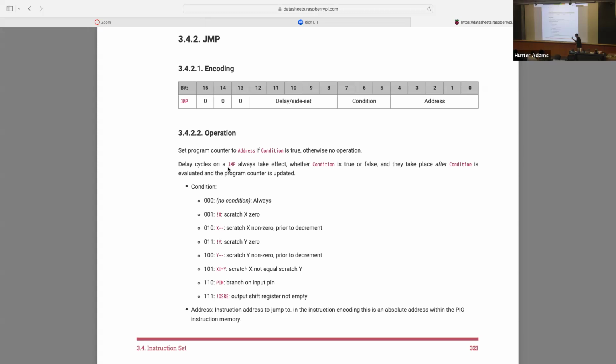So think about this. In one cycle, that instruction that I just mentioned is checking a condition, decrementing a value. We haven't talked about it yet, but you can set it up such that it can simultaneously also manipulate some GPIOs on the side. And you may have a specified delay in there as well. That's like 5 things that single instruction does in one cycle. I don't know exactly how that works. Do you have an idea, Bruce?